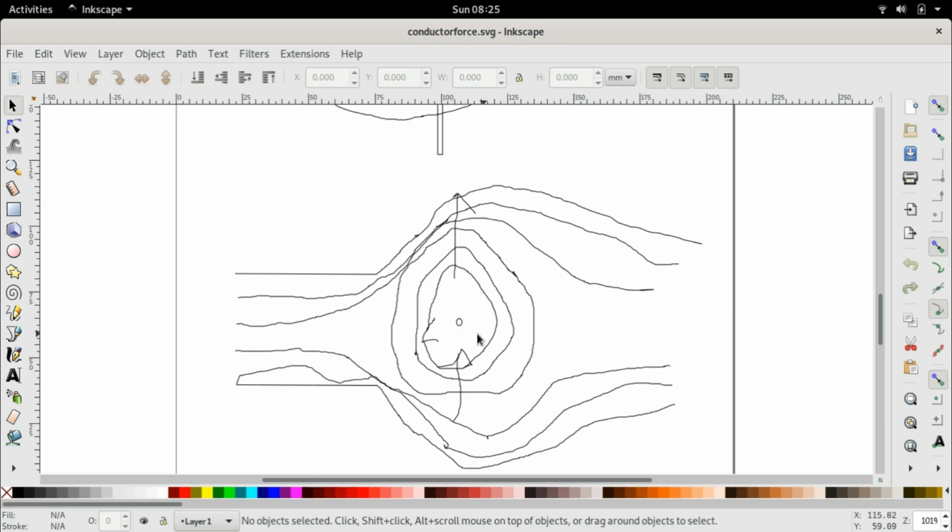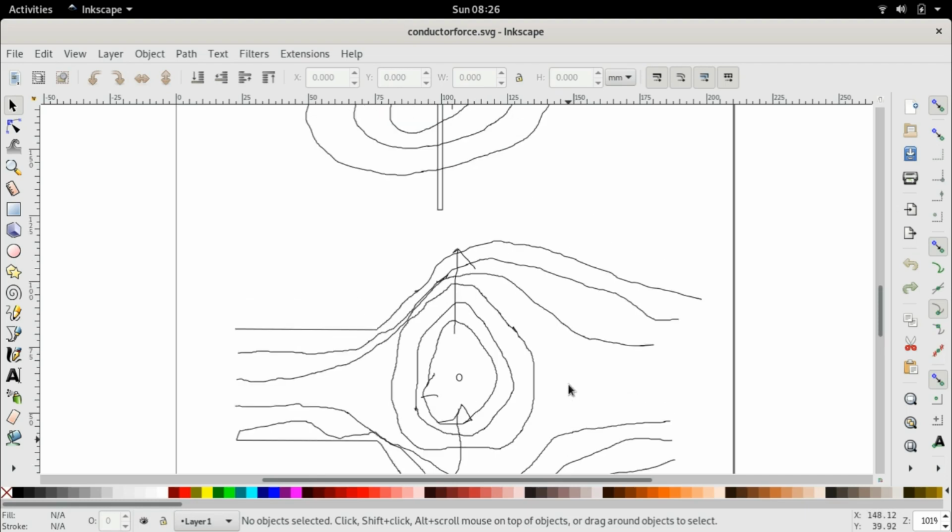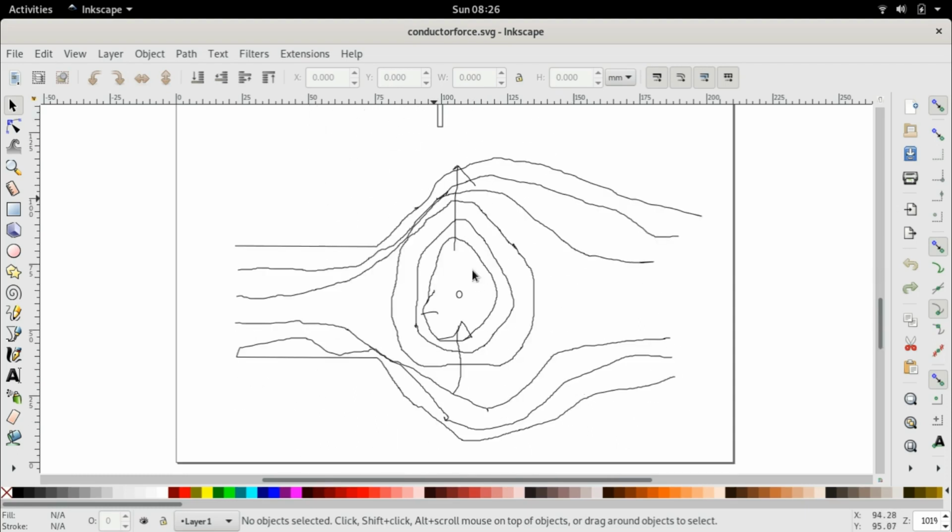So for example, in this case, the magnetic lines of force are getting squished at the bottom and are getting elongated at the top. And quite obviously, the region in which the magnetic lines of force are dense is the region in which the mechanical force is pushing the conductor in the other direction. Therefore, the mechanical force is produced from the bottom to the top. So, this is merely a description of how we can interpret Fleming's left-hand rule. We don't have to start drawing these flux diagrams every time because we have Fleming's left-hand rule.